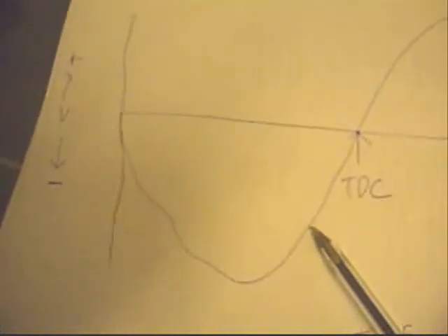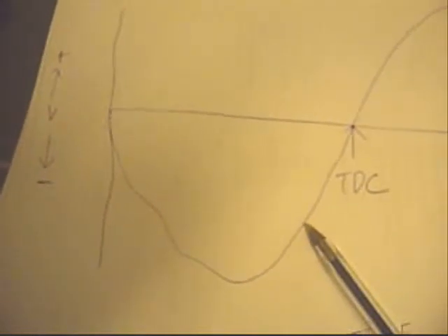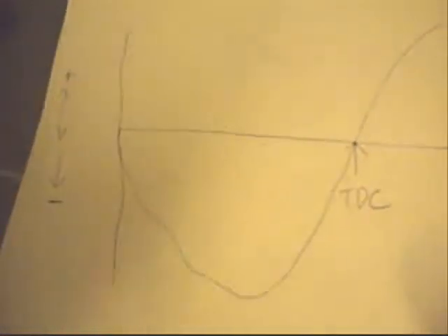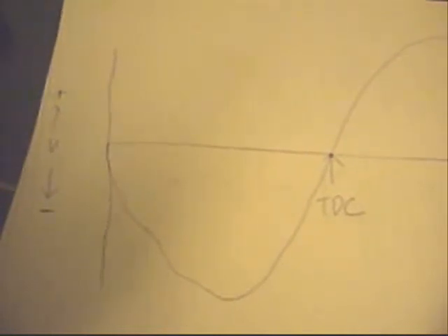Normally that diode that goes from the emitter of the transistor to the base in reverse shorts all that out via your pot. Now on mine, obviously, I get rid of that diode. But anyway, we completely ignore that and look at this bit.